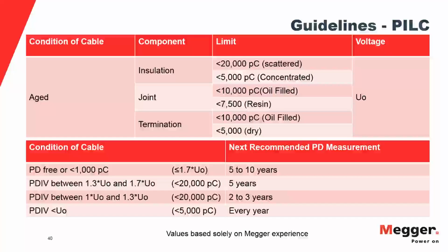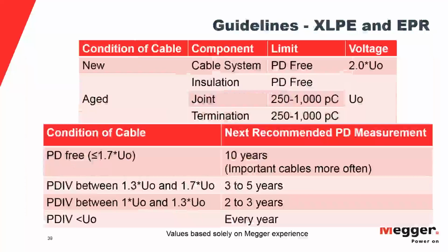And the square wave, the only real application that we have in the field is when you want to do a very quick proof test, like you used to do with the DC high pot, but you don't want to use the DC high pot. Then that's okay if you want to apply a voltage for a very, very short amount of time. But as Jason correctly said, the sine wave is the internationally standardized waveform, as is the cosine rectangular, because that came first.